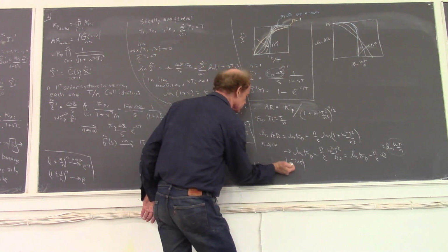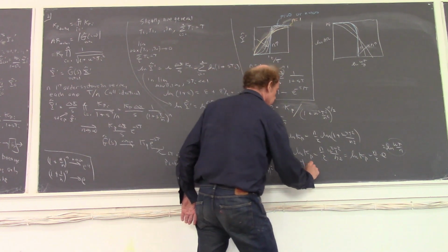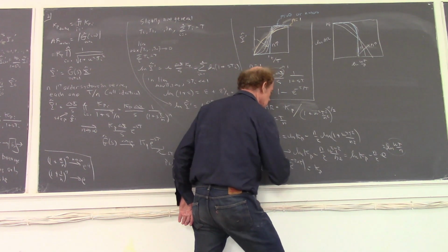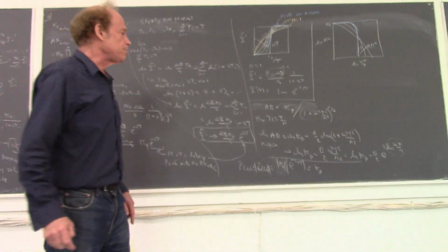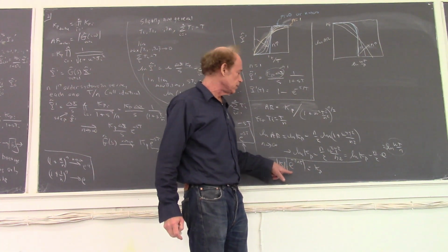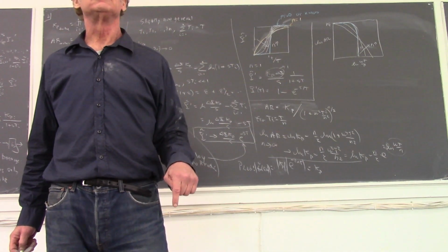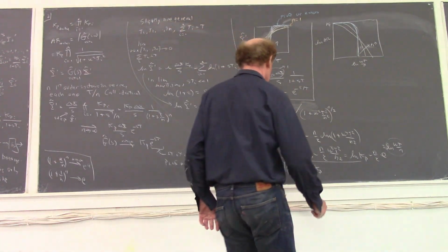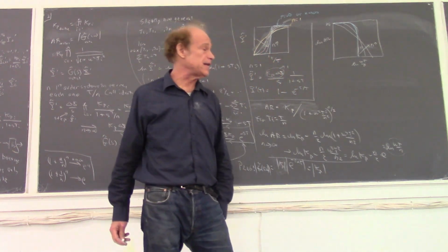This is just Kp times the magnitude of e to the minus i omega t. Well, the magnitude is the cosine squared plus the sine squared. What's the cosine squared plus the sine squared? 1. So this is just equal to Kp, or the magnitude of Kp, because Kp could be negative.